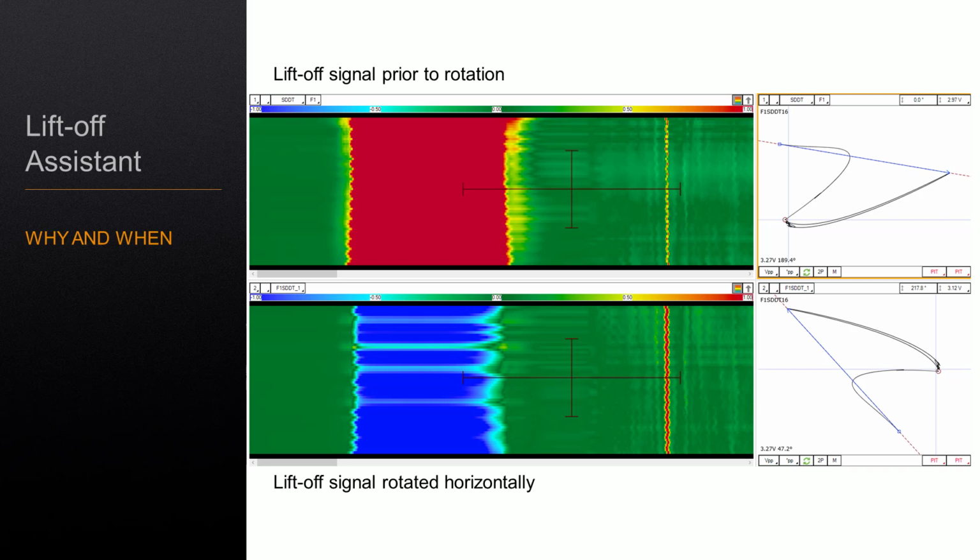In many applications where array probes are used, we also need to use encoders and some type of filters, for example, median filters. And those tools prevent us from getting the liftoff signal rapidly. So when we want to generate a liftoff signal to do the rotation, it means that the probe is lifted from the surface.